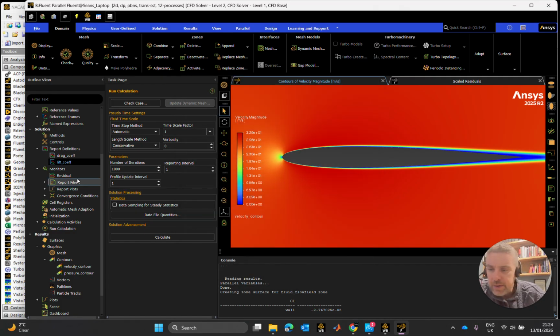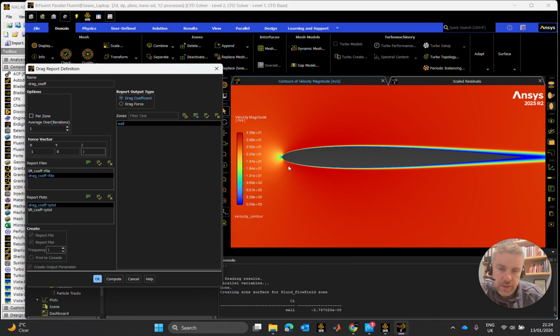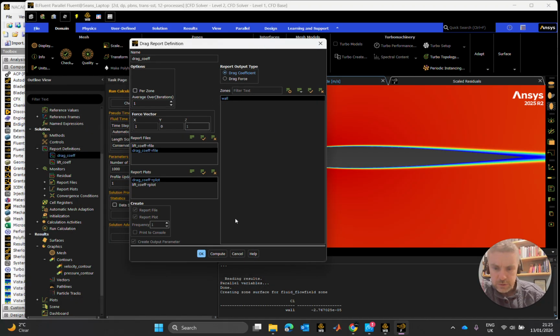And if I went to the drag coefficient, I should see a drag, because indeed I do. I have a pressure drag here at the front. If I looked at the pressure itself, again, we'd see the high pressure region here, but I'll also have this drag here, these viscous effects. This is all pulling the airfoil back. It's preventing the airfoil from running further to the left, if you like. So when I run a compute on that, I should see a value. Indeed I do. It's 0.0158.